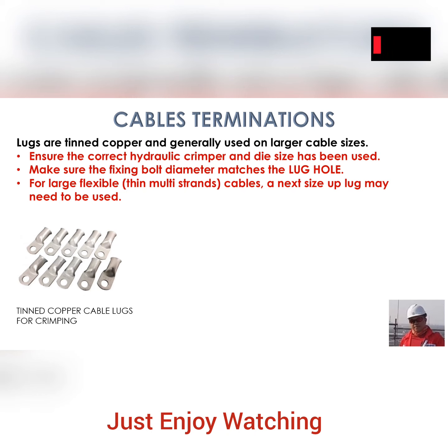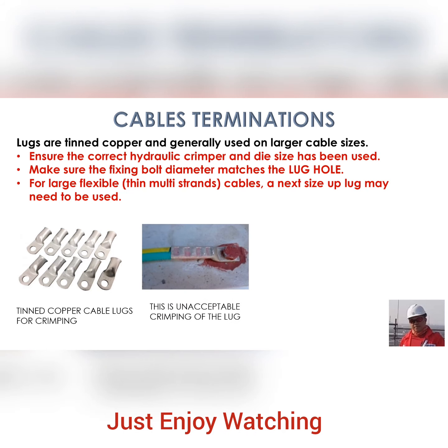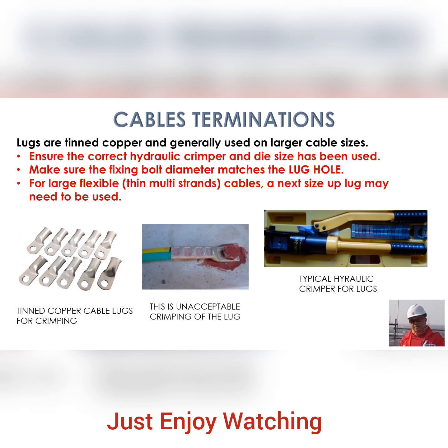So this is the sample of our thin copper lugs that are crimped. You can see here the hole, and then there's a last portion like a circle. So this is how you crimp to support your conductor cable wire. So this is an acceptable crimping of lugs, you can see. And then this is our typical hydraulic crimper for lugs. That is for the big cables, big wires. Okay.